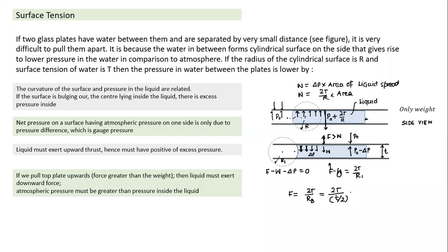And you notice here, smaller the thickness of the water layer is, more difficult it is to pull it apart. It behaves as if there is suction here, suction pressure kind of act. And so I hope you get some sense of what suction pressure means. Suction pressure means the pressure here is lower than atmospheric pressure. It tends to pull the surface in. Actually, it is still exerting pushing force. The contact force is only pushing force. But since it is lower than force acting on the other surface, it appears like a suction pressure.